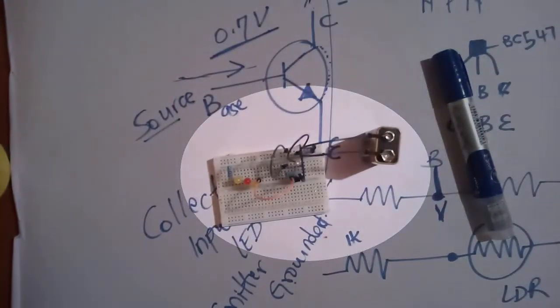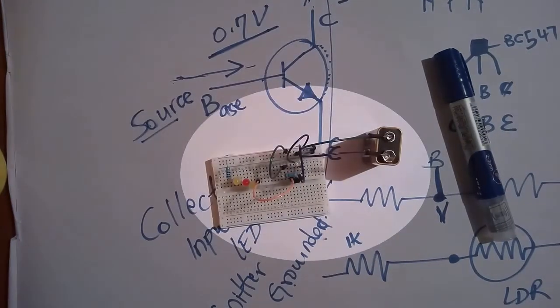So basically, today we are just dealing with something simple just to get me started back up. We are looking at an LDR and a transistor as a switch. An LDR is a light dependent resistor, which means it's a resistor, but its resistance increases or reduces depending on the light intensity. The transistor can act as a switch, which is how we're using it today. It can also act as an amplification tool. Today we are working on a transistor as a switch, and we are controlling LEDs with an LDR.